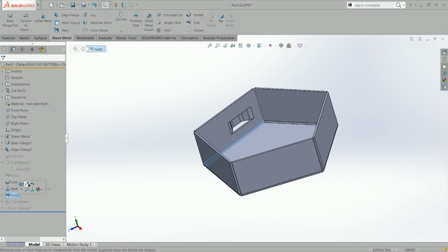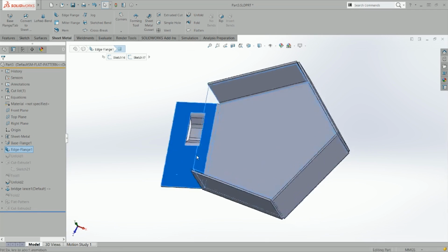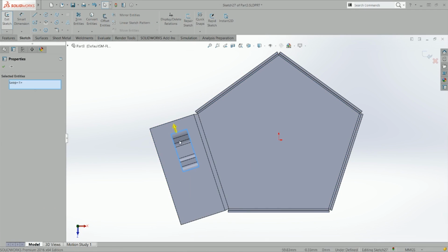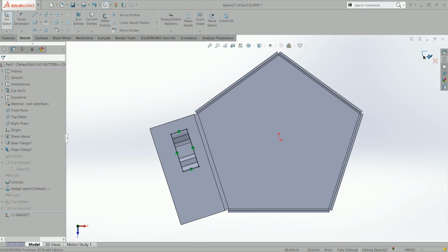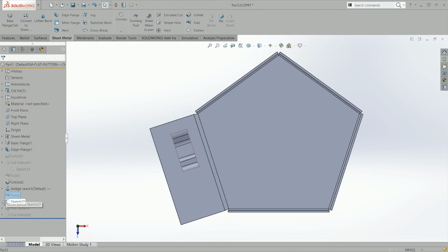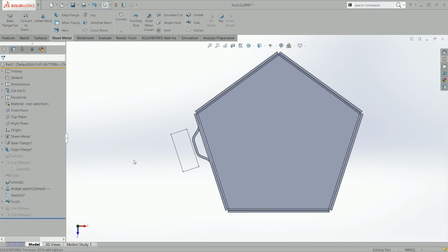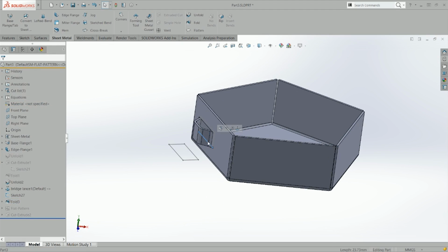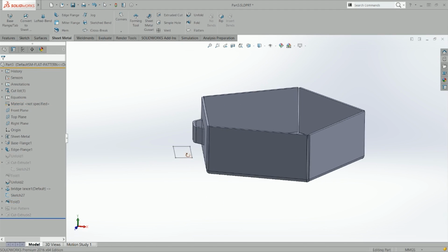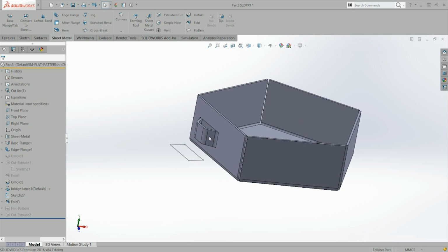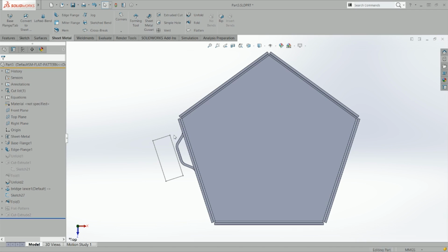If you go back to this one, you can actually make sketches or references from here. So if I make a loop here, I'm gonna convert geometry, get out of here, just move, delete my fold feature for a little bit, and then fold it back again. As you see, we remain with the actual shape of the lance form or any other form. So you can actually start designing from here.